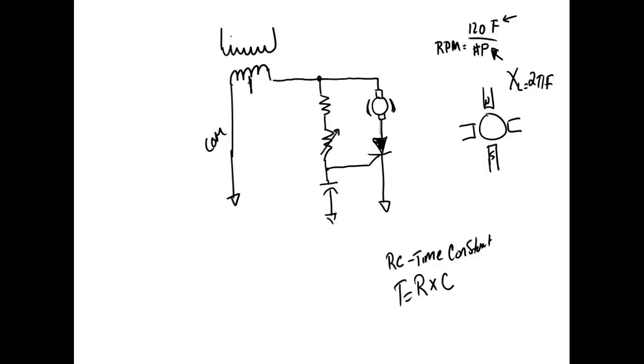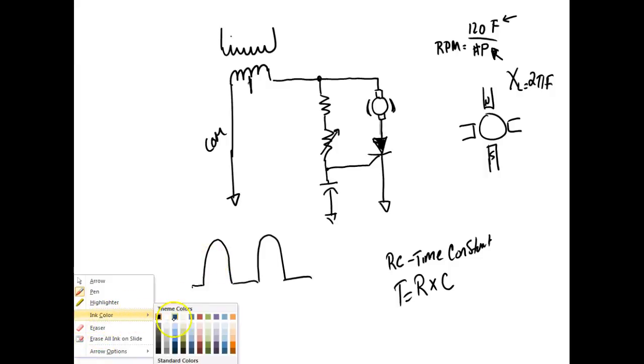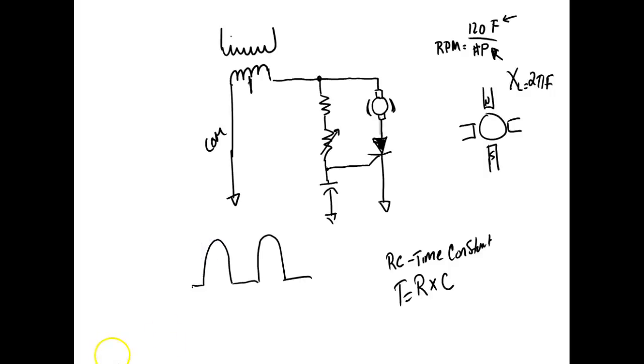You'll understand that. So this little SCR circuit, what we're doing is we have the armature, we have a permanent magnet motor, and what I'm doing is I'm delaying the firing of the SCR. And if I delay the firing of the SCR, then what we're doing is we're turning it on later in the cycle, right? And of course, we looked at this, but it's half wave. So what we're actually getting on this, if we turn it wide open, then what we would get across the motor is we would get this, right? You understand? And then if I delay it with that capacitor, then what I'm doing is I'm letting less of the AC go through.